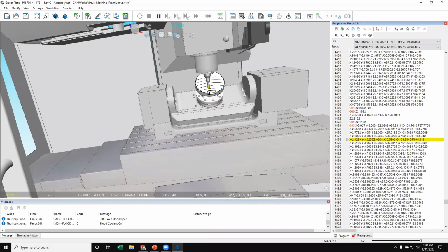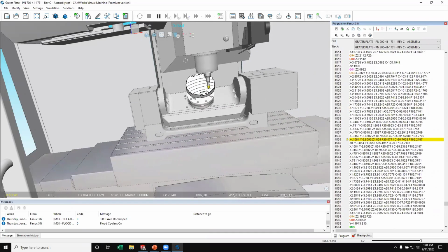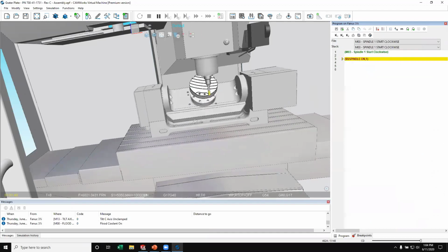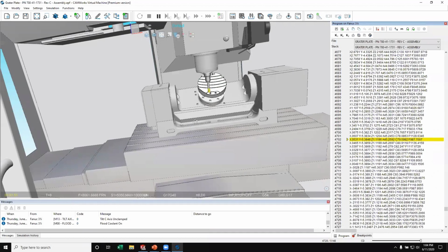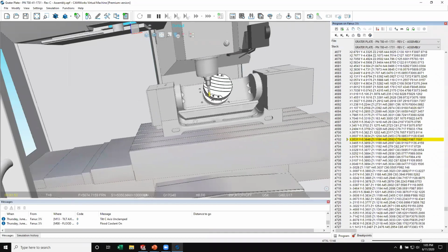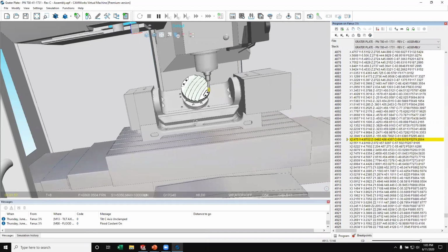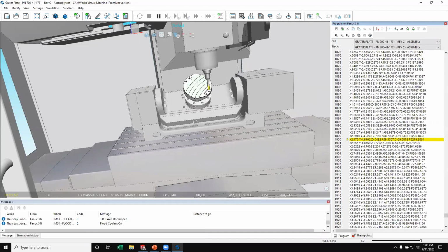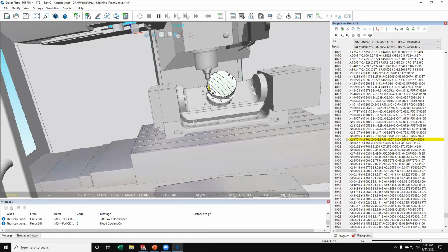And in case anyone was wondering, it would alert me and tell me if there's a collision if the back of this part were to hit the tool, the machine or something. That's why it's critical to model your machine and have this. This is, like I said, one of the more costly upgrades. A lot more work involved if you model your machine. And the more accurate you model your machine, the more accurate you can simulate it. And of course, when you're checking clearances, you want an accurate model of everything, your machine, your tool holder, etc.